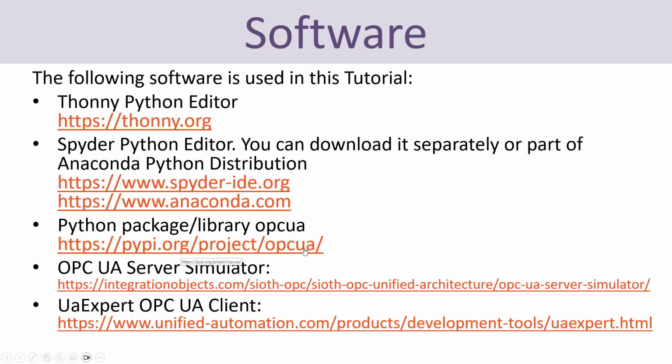But basically you just install it using the pip command or the built-in features in the different Python editors. We will use this OPC UA Server Simulator as a demo OPC UA server when testing our OPC UA clients that we are going to create in Python. We will also use an OPC UA client called UA Expert in order to test the system and make sure that everything works as expected.